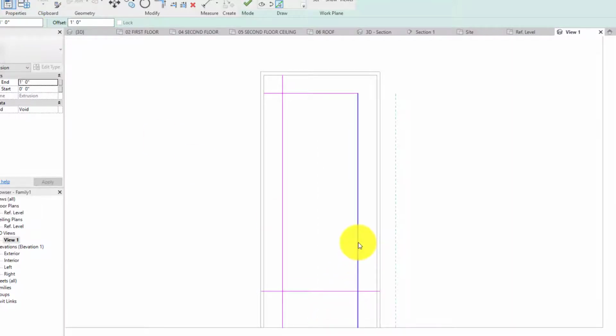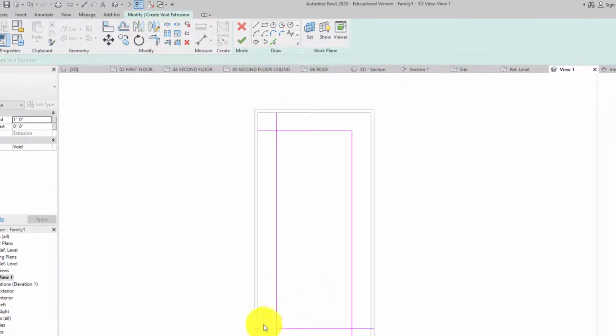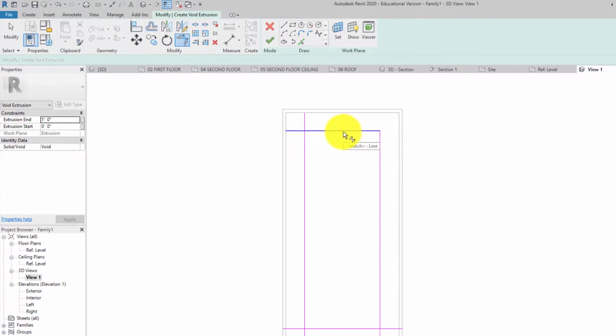All right. So, new tool, like I said before, you have to have these lines all in one nice completed shape, and these are not, because these endpoints don't line up with other endpoints. So what we're going to do is go to the top where we have Trim/Extend, and how this works is you always click what you want to keep. So I want to keep this line, I want to get rid of this, so I'm going to click here, and then click this line down here and watch what happens. It gets rid of both of those. Now down here I'm going to click here and here and here and here.